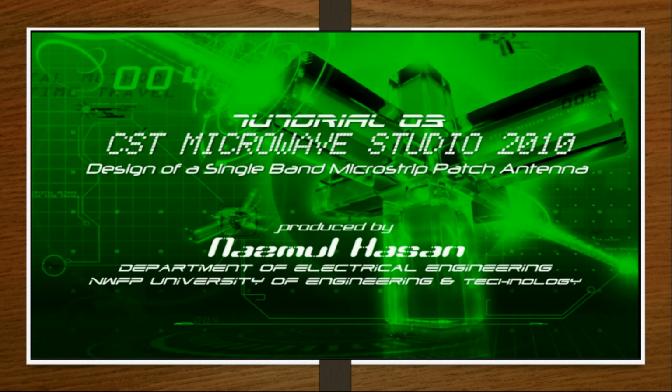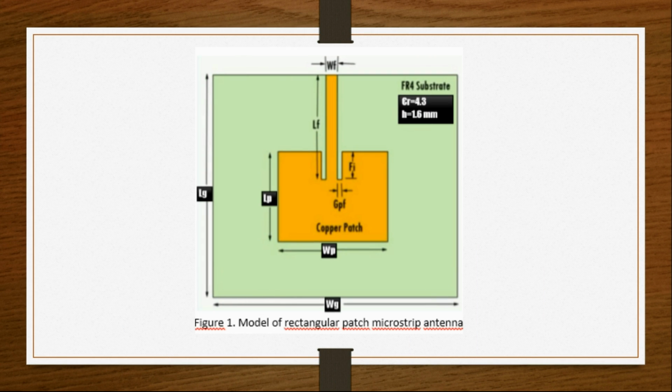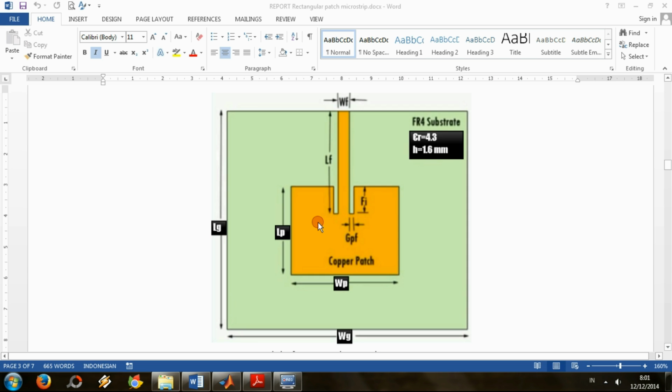So here's the design. Basically, a rectangular microstrip patch antenna consists of three parts: the rectangular patch, the substrate, and the ground plane at the back of that. And I use an inset feed line here. The dimensions of the patch are WP for width and LP for length, and for the inset feed line we have the gap GPF, the length LF, and the width WF. And for the ground plane and the substrate, the width is WG and the length is LG.